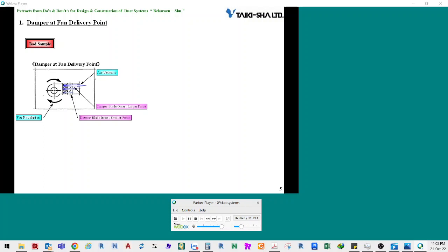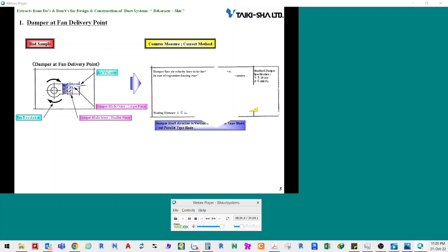The damper axis is sideways from the direction of the revolution of the fan blades. In this case, the wind velocity is faster at periphery positions more distant in the direction of the centrifuge from the center of the fan blades. If duct blades are installed so that the axes of the duct blades are sideways from the direction of the revolution of the fan blades, inner blades receive the wind at lower speeds, while outer blades receive the wind at higher speeds. Different forces are therefore applied to every blade. As a result, excessive force is imposed on the damper and may cause breakage.